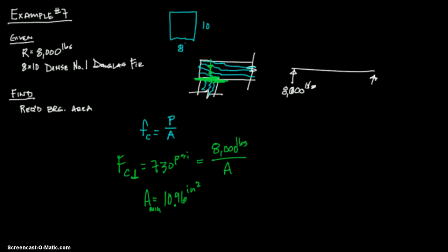I'll change the color. We know we have an 8 by 10. And let's look at the nominal compared to the actual dimensions. And the actual is 7.5 and 9.5 inches, of course. All right, so this was our theoretical answer right there. And usually that's going to get you just fine, but let's go ahead and turn it into a real world situation like I just said. And 7.5 inches is actual. So if you're thinking about it, you're already going to have 7.5 inches deep.